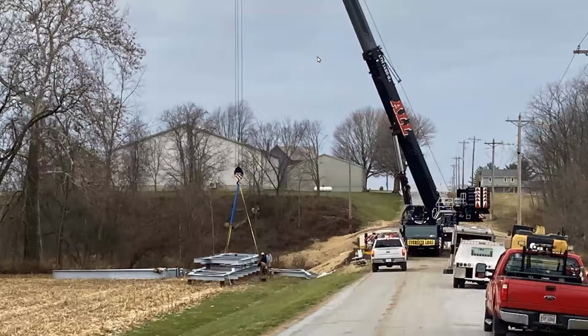And this is a pretty common scene when we're erecting a truss bridge in Ohio. We're going to set up usually on the roadway many times if we can. We're going to use farmers' fields or undeveloped quadrants of the site to bring in our field sections. We're going to splice those together into one full truss girder. Pick that up. This particular crane was a 450-ton Liebherr crane.